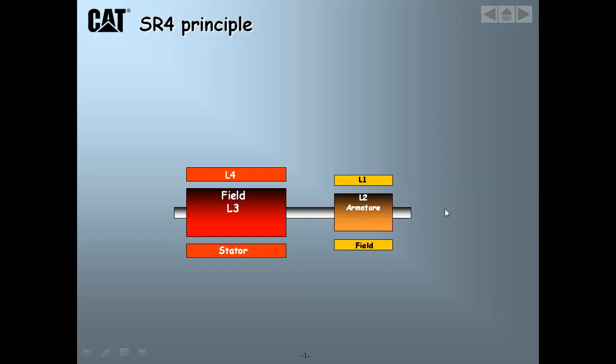Okay, sir. Thank you. The main generator consists of two generators, the main one and one for excitation. When producing electricity, the output at the rotor will be rectified to DC and supply the rotor of the main generator to create the magnetic poles. When these magnetic poles rotate and cross the field, the stator of the main generator produces electric current on it.